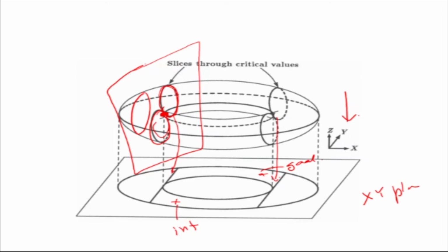Now how do we go? If this is my silhouette curve, the side boundary which I'm getting, these points I've got, right? So from here I can go like this, I can go like this, I can go like this, and I can go there. So this silhouette curve is actually giving me the path which I can follow. This is a type of roadmap now. I'm going to start from the initial point, go like this, follow the curve here. That's a straight line which is having a critical point. Then I cross over here, I go like this, and I go there.